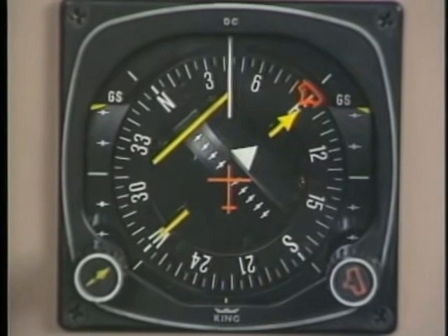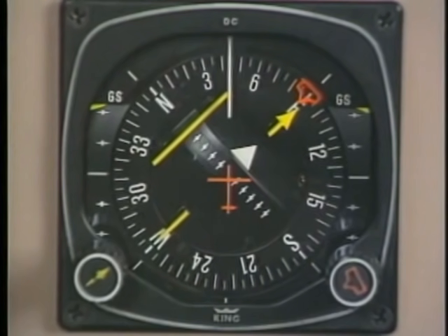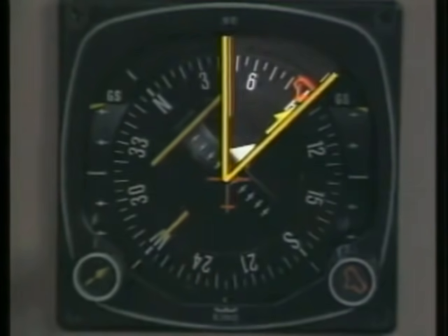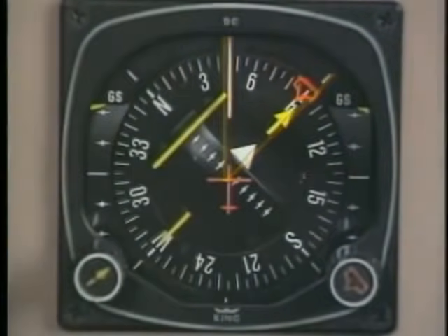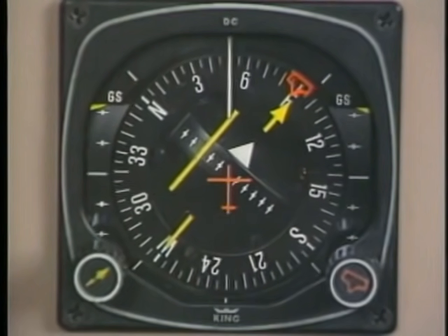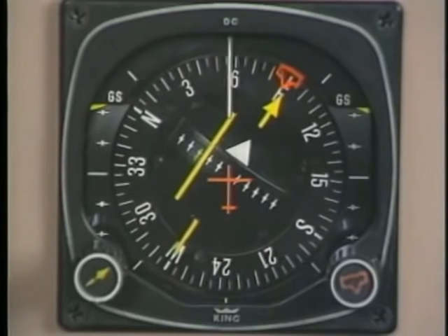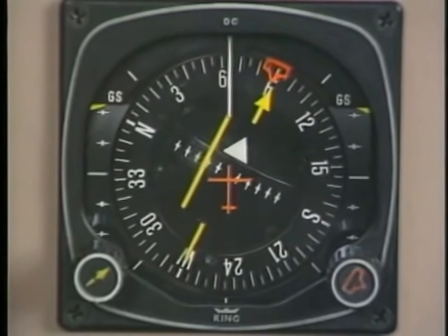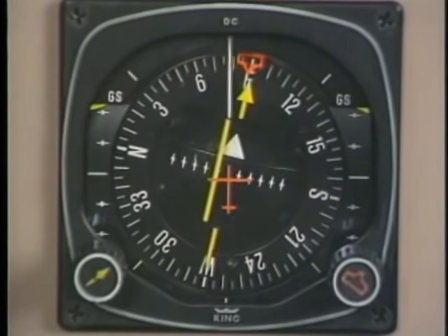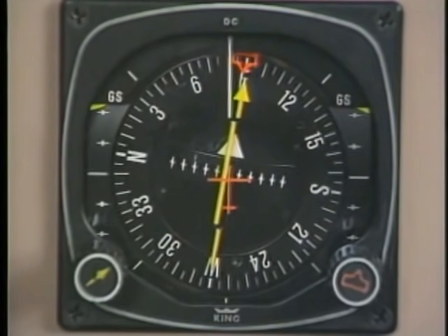Let's assume you want a 45-degree intercept. After turning the airplane to 045 degrees, notice how the instrument shows your angle as well as your new heading. As you approach the radial, the needle will begin to move towards center to signify that you're nearing the course. You can gradually shallow the angle depending on your rate of closure to smoothly intercept the new course. You might have to adjust your heading slightly to compensate for the wind.